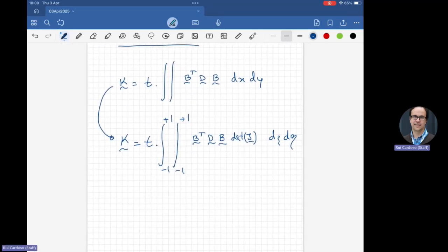And also for the numerical integration, you remember when we did the strut, we did this volume integral. We calculated the length of the strut. We multiplied the length of the strut by the area of cross section. So we have the volume of our strut, right? So now we are doing a very different approach. We are doing an approach that works for any type of element. This isoparametric approach, and this numerical integration we are going to do, works for any element.